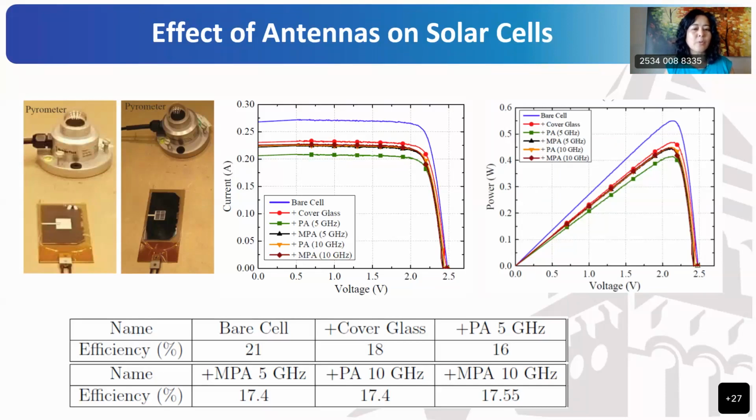So here we were able to go back to the system engineer, the power engineer, and say, look, if we make our antenna 90% transparent, in fact, we can make it 95% transparent, then the blocking of the solar power generation is less than 3%. And that is comparable with the shadow cast by those long wires that stick out, because they also cast shadow, right? Even though they don't block the solar panel, when the light comes oblique, it casts shadow. So it's comparable to the shadow that you are already losing.